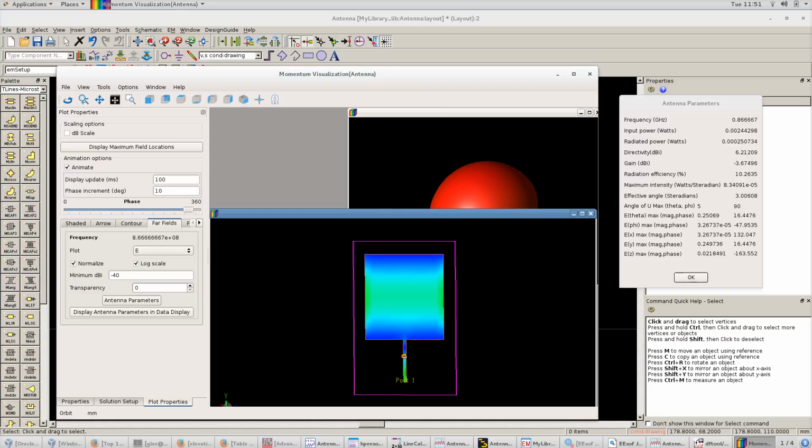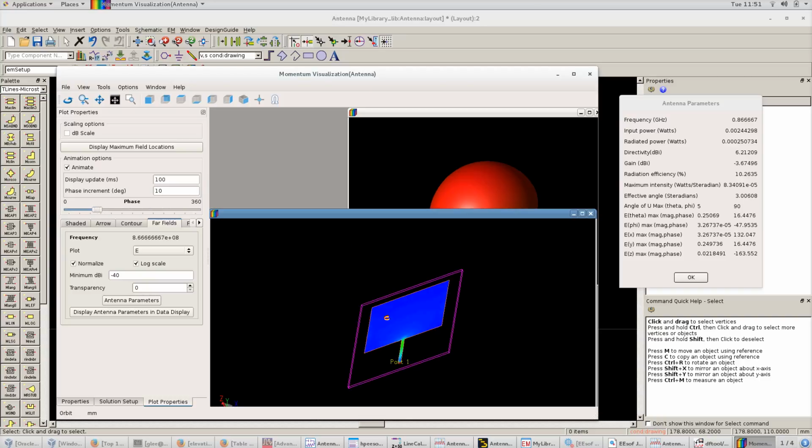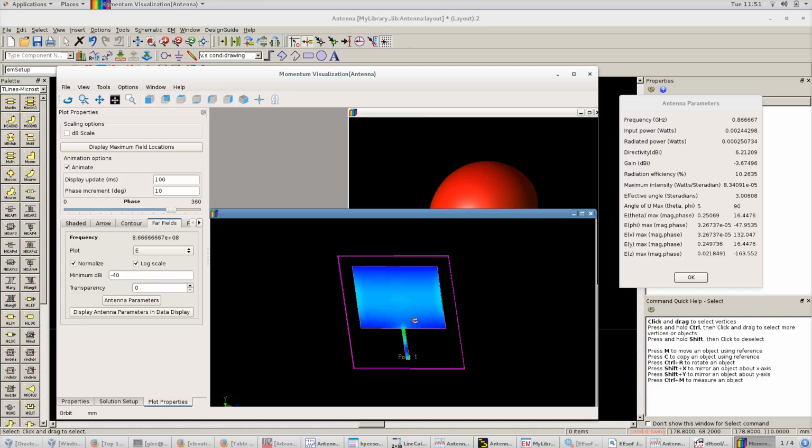There's a fair amount of loss on this transmission line. So if I want to make this better, I might want to shorten the transmission line, or maybe even just change where my feed point is, because I'm probably getting some reflections right here at the input to the patch surface area. I can go into some of that in detail during the lab if anybody's really interested in how you would want to go through and make this thing a little bit better. But there's a lot of things you can do to make this simulate a little bit better than what you have currently.